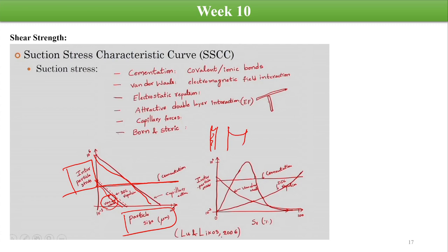Against the saturation value, if we plot, we'll see that cementation does not depend on the saturation, it will be constant throughout, and the diffuse double layer will increase as the saturation increases, and the van der Waals forces will decrease as the saturation increases, because the distance between the particles will increase. Then some forces, such as the capillary forces, first increase, then decrease, right?